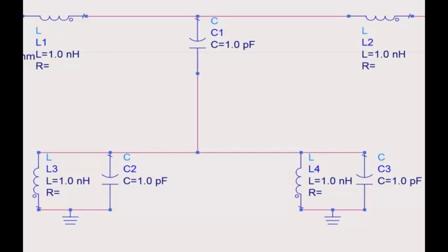This figure shows the equivalent circuit diagram of a split ring resonator. This represents the first split ring. It's a combination of L and C. This is the second split ring. It's again a combination of L and C. And here are two inductors, the surface inductance and the bottom strip line inductance, and there is a capacitance in between them.